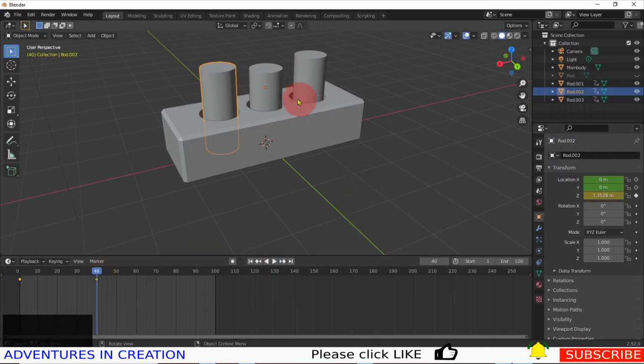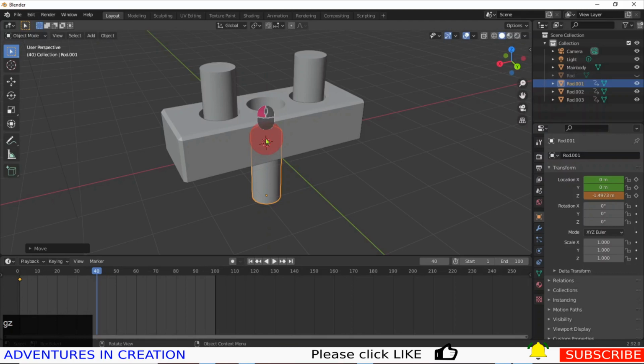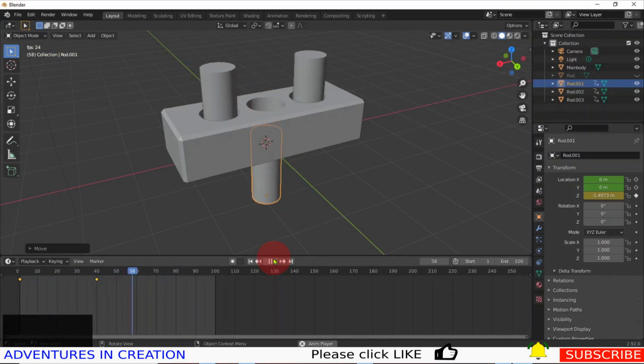And then I'm going to select this guy and give him G and Z and pull him down to where I want him to be. And then give him a keyframe. Now, if I wanted it to be the exact same amount of offset as this guy, I can set these numbers if I want to, but I'm just doing it by eye because it's very simple. So if you watch now, it starts there, pops up, and then it stops. Well, we want it to go back to the beginning.